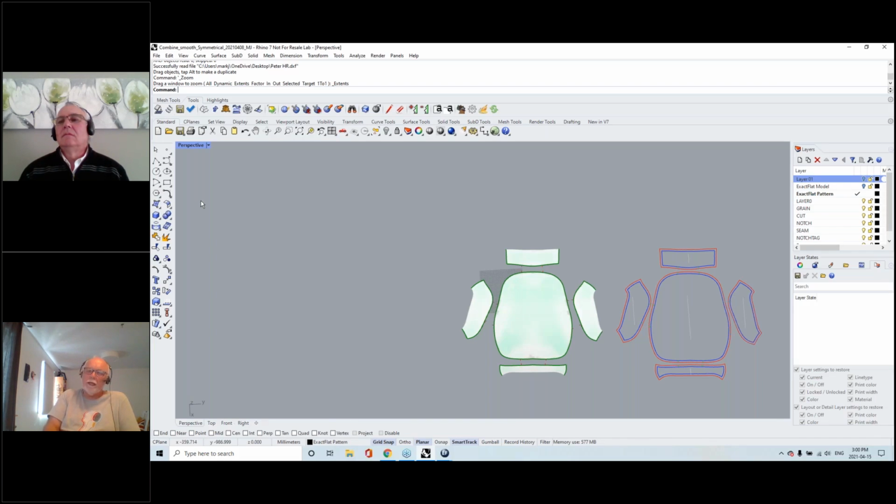But if I was to scan a soccer ball, which is perfectly round in theory, the scanner can't know what point of view it has on that. But if I pointed at a human face, it knows immediately because there's geometrical detail. So it can tell that it's moved sideways, but it can't tell if it's moving along a flat table. So we always use targets.